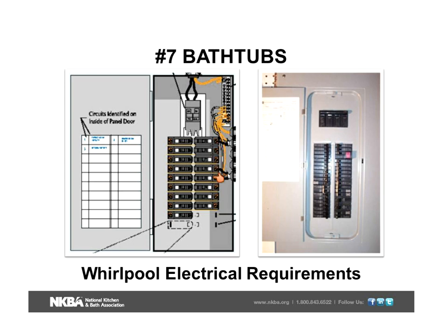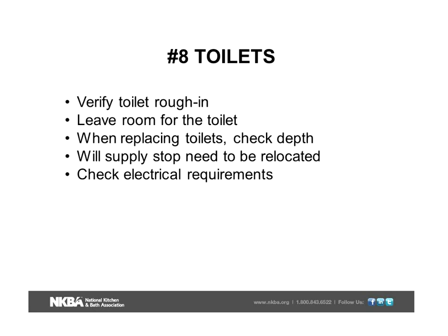Don't add the breakers up to come up with 200 amps or whatever the size of the panel is. It doesn't work that way. And the electrician can tell you if adding that is going to overpower the panel. And I'm sure that if I ask the electrician, oh no, you've got so many light circuits on different circuits, and I did that on purpose. If one set of lights goes out before I can get a breaker fixed, then I've got other lights within that space. So do check that panel to see if you do have enough electricity. To put a new panel in, it could cost $2,000. To put a breaker in, it's not that much.